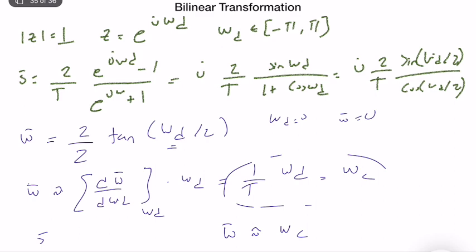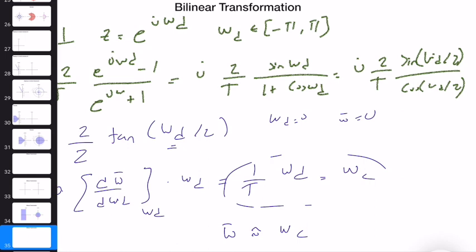And then we will go back to the Z domain and implement it on our system. And the good thing is it will give exactly the same gain and phase margins. So this is the whole idea. And I will talk about these frequency-based details later. But for midterm 2, or for the simple step analysis, this is the whole important point.